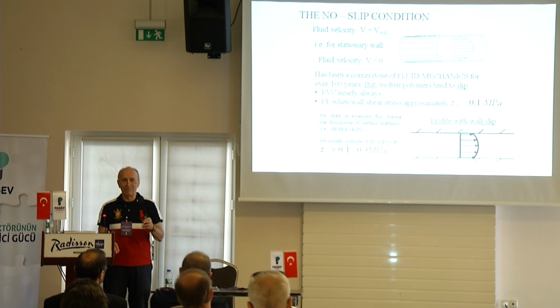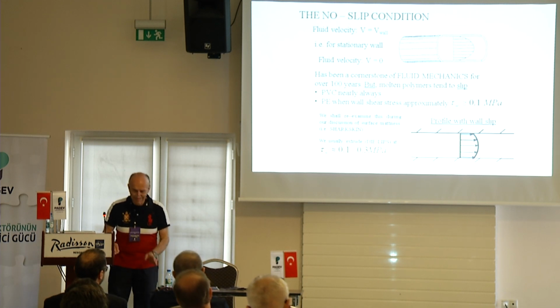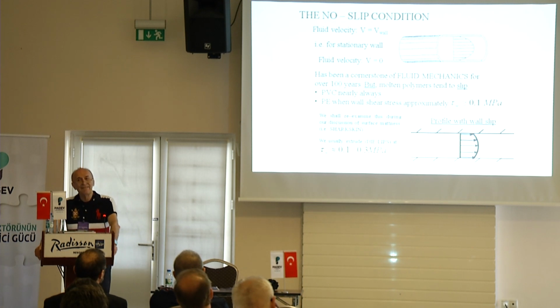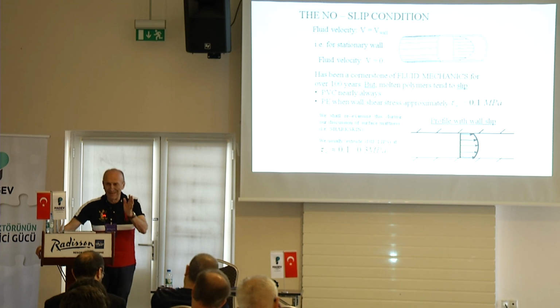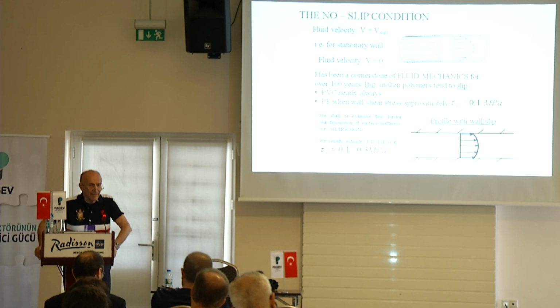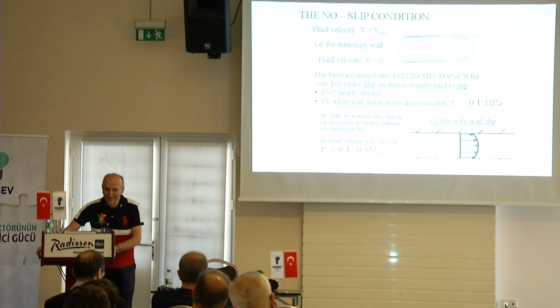However, yes, if I'm dealing with water, if I'm dealing with air, I can deal with oil in pipelines, this boundary condition is correct. With polymers, you know, polymers behave in very strange ways. Polymers nearly always exhibit some wall slip, and you have to measure it.